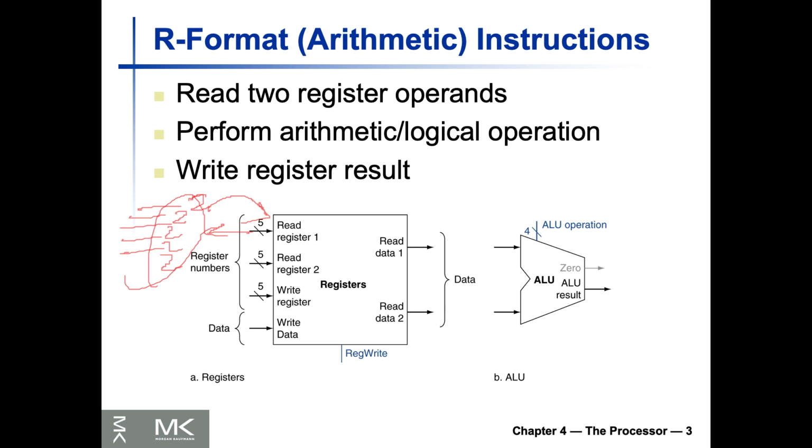Also, I did mention that because we are following this convention for both reads and writes, and since writes to the register files are edge triggered as well, this design that you see here can actually do a read and write at the same register within the same clock cycle. Okay, so our read will get the value that was written in an earlier clock cycle. So in one clock we write, and then right after that we can read, both on the edge triggered convention. And data value lines are also, of course, 64 bits.